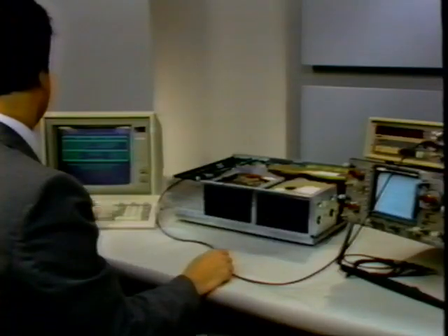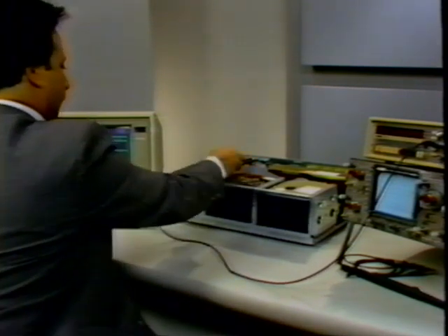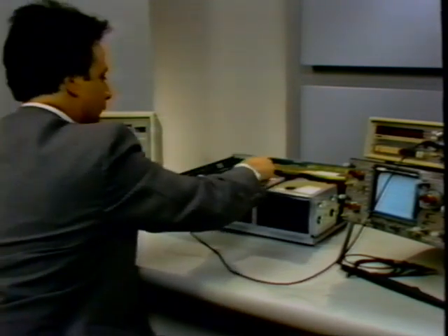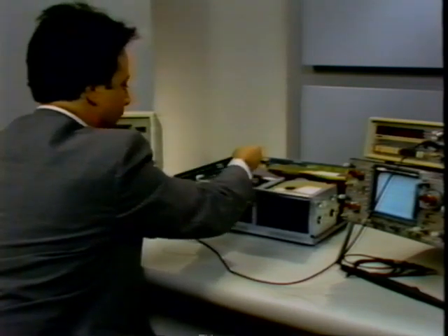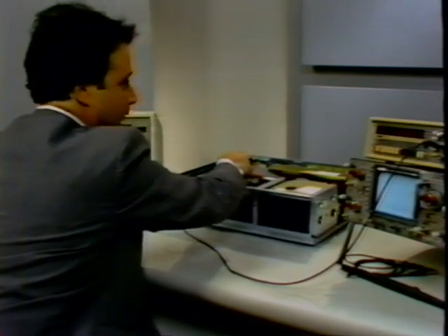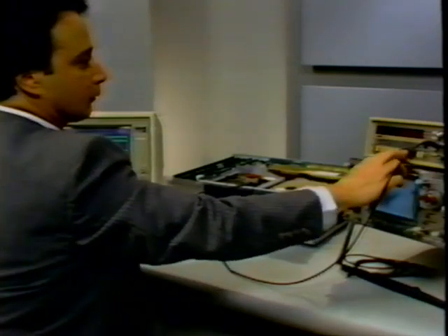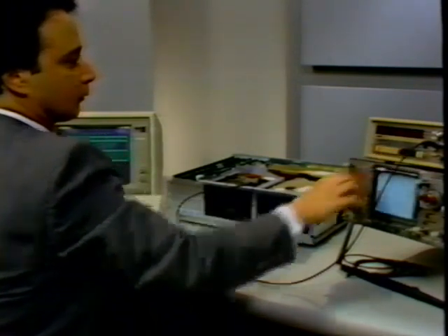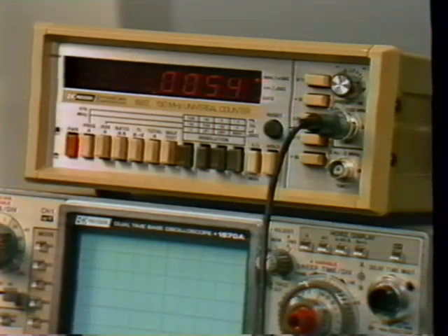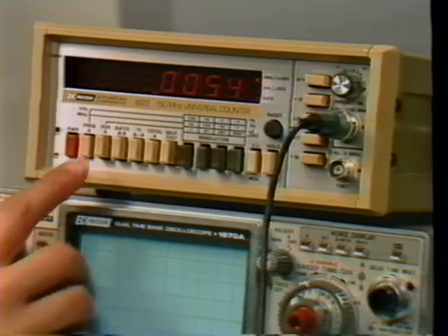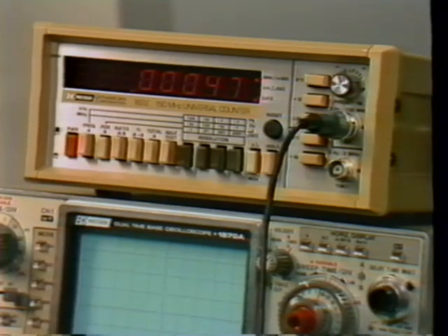Now that you are familiar with the frequency counter's controls, let's watch its correct use. As an example, let's measure the motor speed on a 5 1/4 inch floppy drive. Set the probe to the times 1 setting, since the signal to be measured has an amplitude of less than 20 volts. Next, find an appropriate ground point. To find motor speed, observe the index pulse coming from the drive. Since this pulse has a fast rise time, use the period A setting to measure its period.